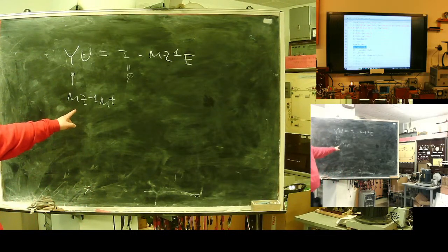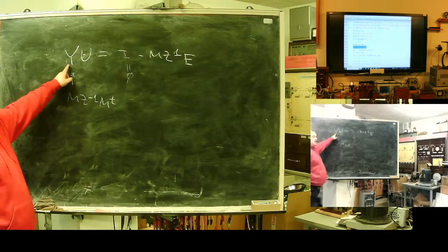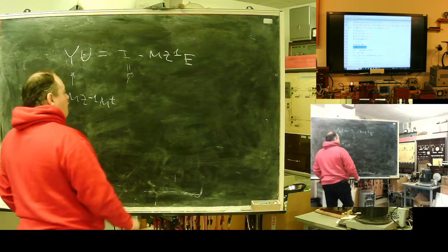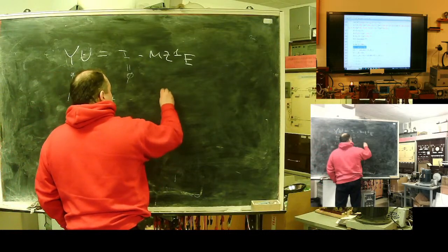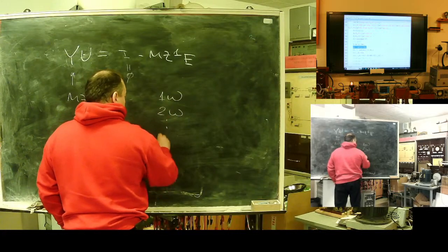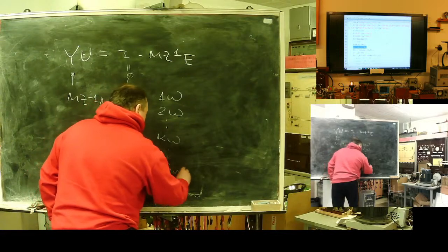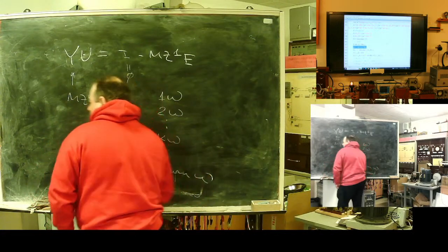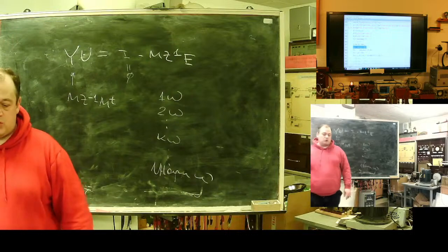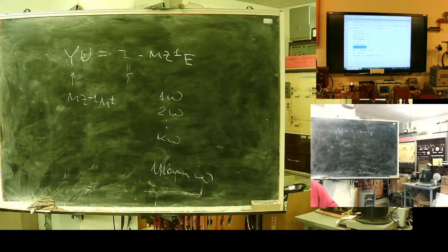It's a nodal admittance equation system, or equation system of the nodal admittance technique. I will need to solve it for frequencies starting from 1 omega, double omega, and so on, k omega, ending with n half omega. Actually, I will need to solve it 70 times, for each of the harmonics.